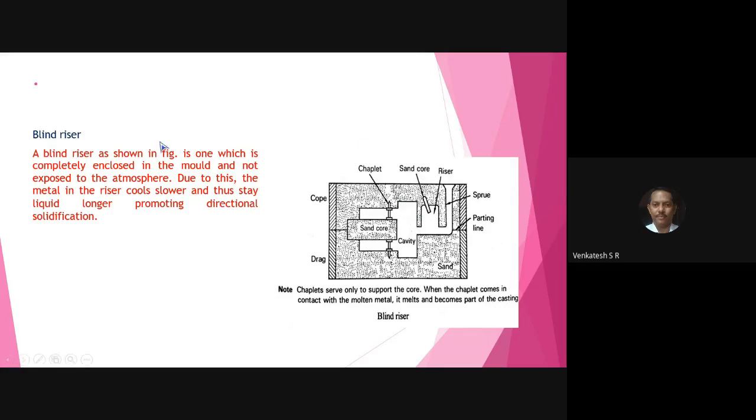Usually, they bring 26 or 27 kgs of liquid metal in the ladle. When they empty the ladle, they understand that the mold cavity is completely filled with the liquid metal, only leaving 1 or half kg of liquid metal in the ladle or in the sprue or in the pouring basin. So from that only they understand the liquid is filled in the mold cavity.